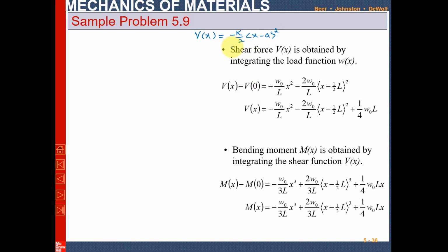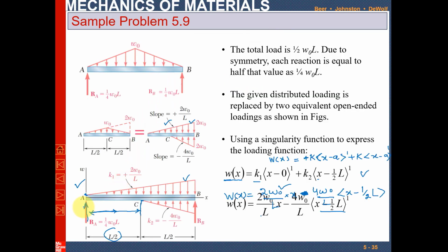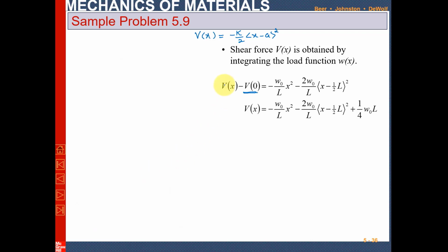Again, for both the loads, initially neglect this. So this is for concentrated load. There is a concentrated load at the start as well, so we have to encounter it as well. So Vx minus V0 is equal to minus w0 over L into x square minus 2 w0 over L into x minus 1 over 2 L whole square. So this was the general equation for the shear force.